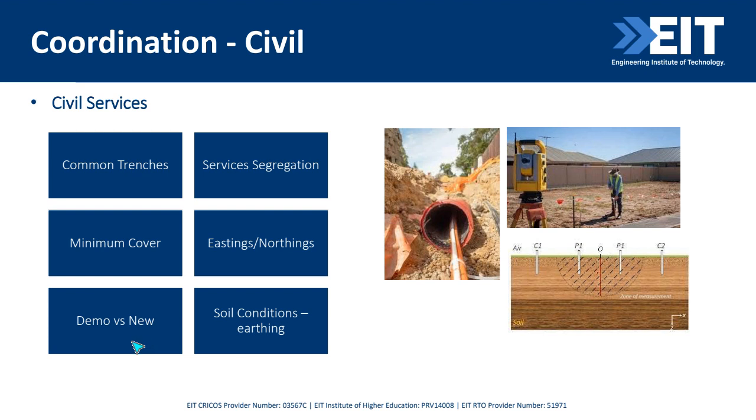And civil is also very familiar with the soil conditions. So we need to know that for our earthing design, more so for high voltage, but it plays a role in lightning protection, such as our earth resistivity values. How conductive is our soil?